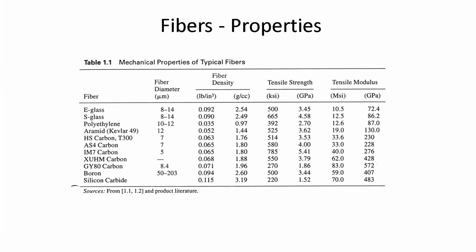Here, what I show, and this is a great plot, is a table. It shows the tensile strength and tensile modulus across a range of fiber systems. And what you see here, for example, is I have e-glass, which has very low tensile modulus compared to everything else. And then we look at how e-glass compares to carbon in terms of strength, and it's not that off.